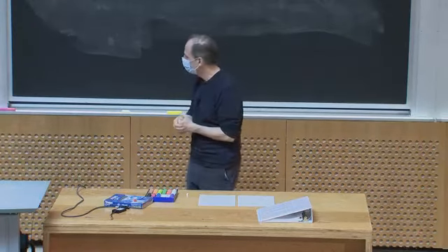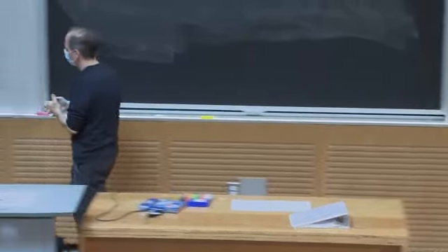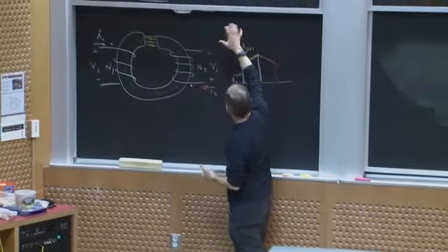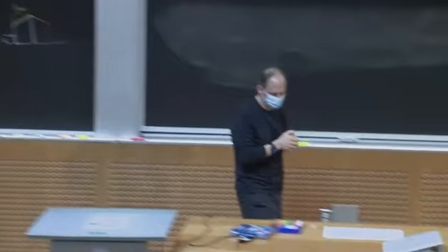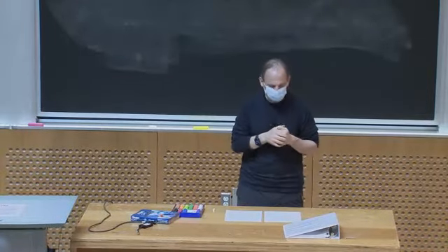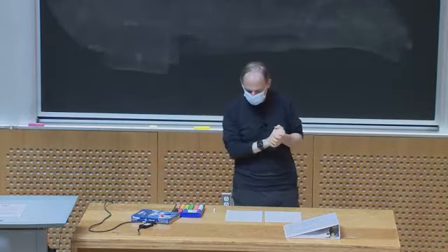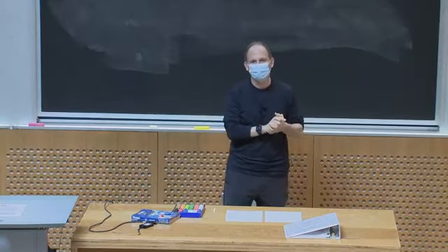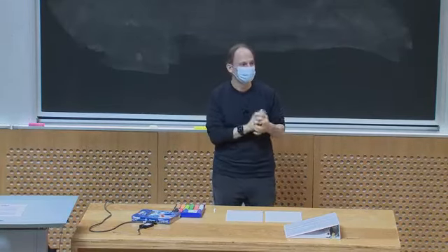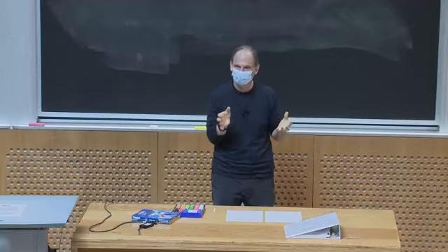Okay, and like we said, because we have this nice isolation, I can reference the secondary either for positive or negative output voltages as I choose. We get our nice ground-referenced active switch. The other thing I didn't mention is why would we want this turns ratio? Because it can help us really design the converter better.